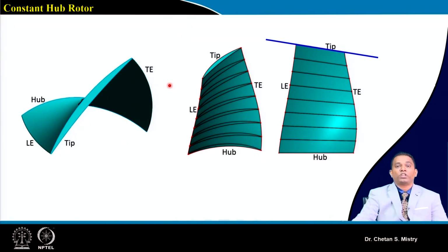Same way, this is my transonic compressor. That's the reason why we have selected a DCA aerofoil. And here, if you look, this represents how my blade angle varies all the way from hub to tip. There is still scope: you can modify the loading near the hub and reduce this turning angle. Now this represents my constant hub diameter configuration.